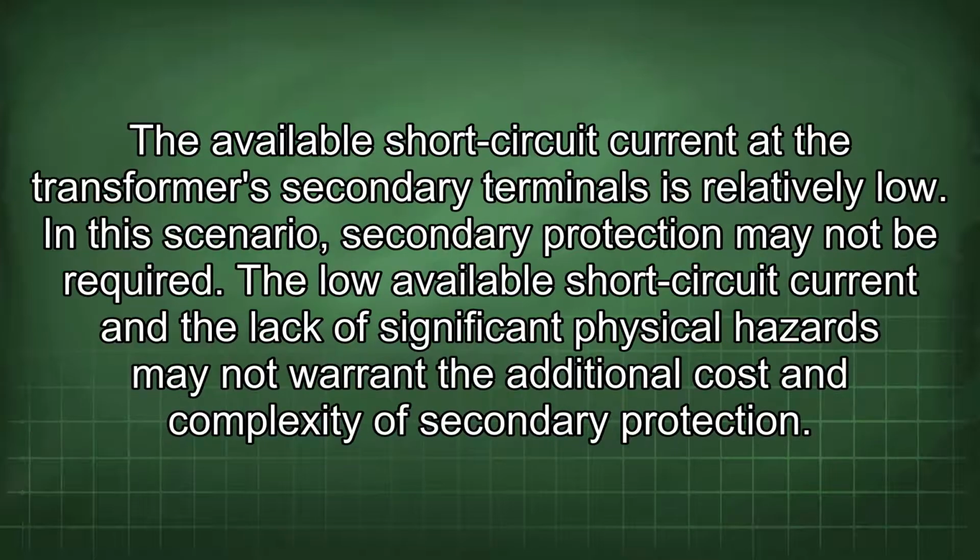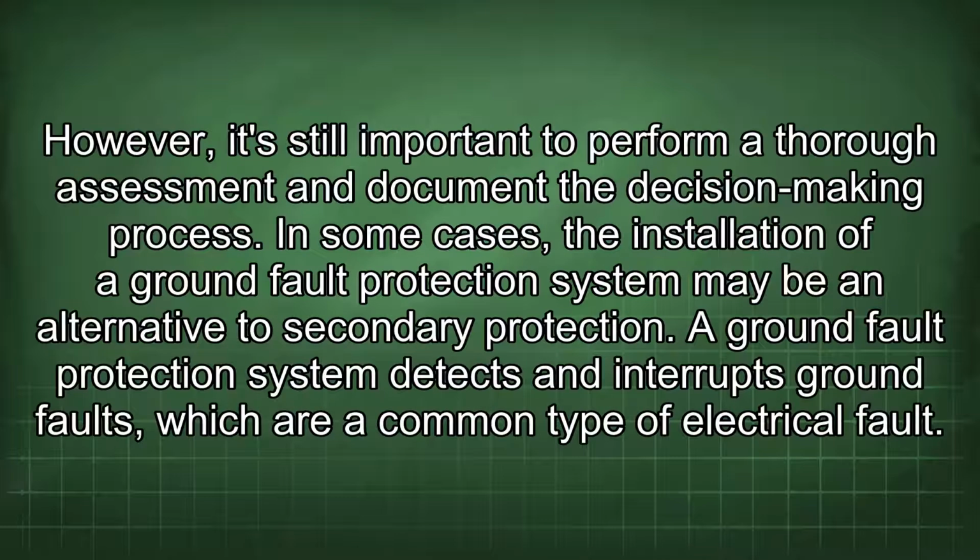The available short-circuit current at the transformer's secondary terminals is relatively low. In this scenario, secondary protection may not be required. The low available short-circuit current and the lack of significant physical hazards may not warrant the additional cost and complexity of secondary protection. However, it's still important to perform a thorough assessment and document the decision-making process.